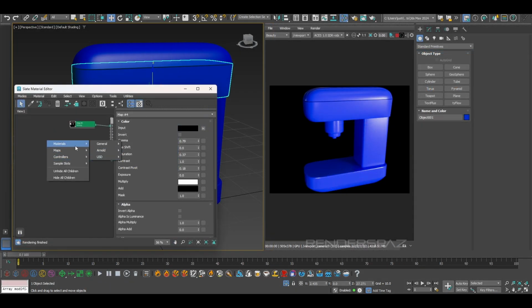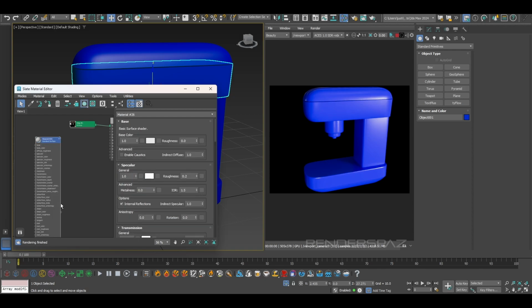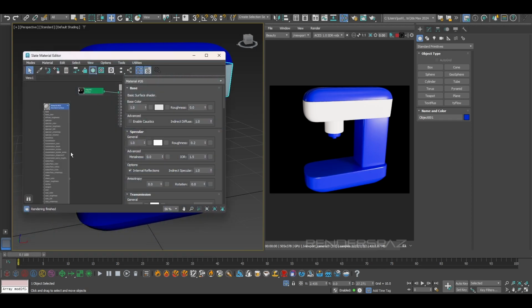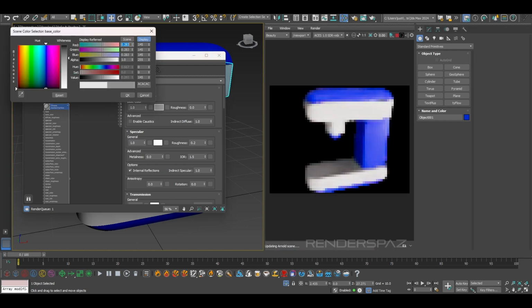Alright, so I'm going to use a color correction node on the HDRI image and just brighten that up, and then also gray it out just a bit, or desaturate the colors. And now, once that's all complete, I can add in some of the material. So we're going to start off with creating our chrome material here.